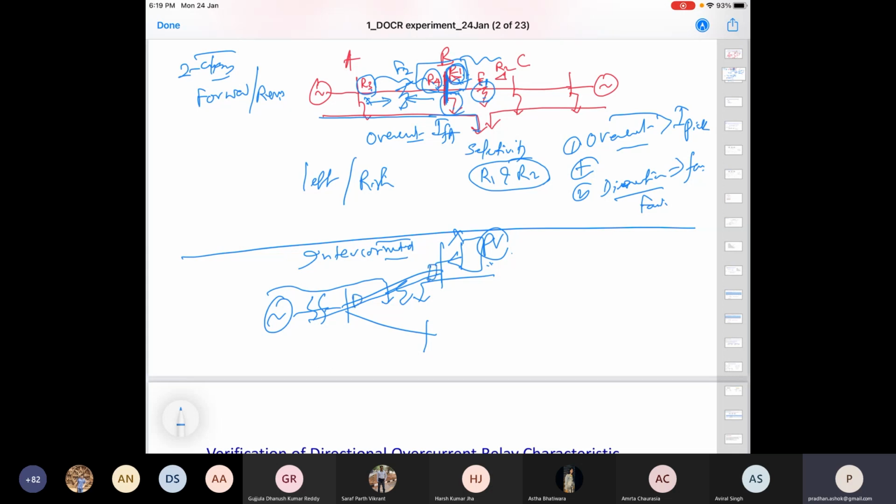So you require breakers at both the ends, and also an overcurrent relay with directional features in this case. So the protection philosophy, the protection strategy, has to be different now in the scenario of these renewable integrations, more and more numbers in the distribution system, or even in the transmission system.